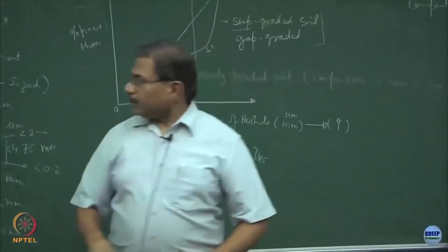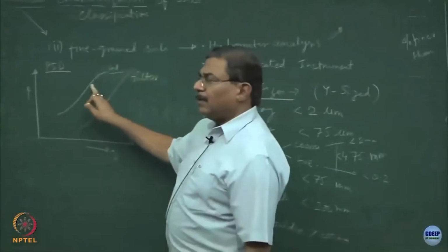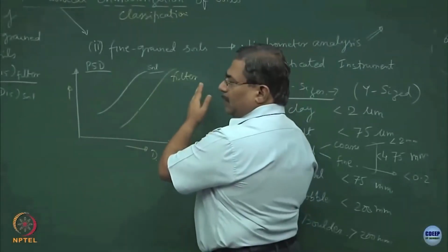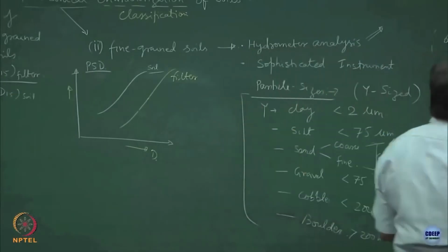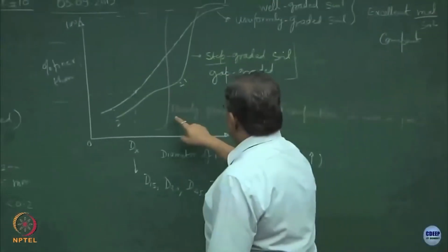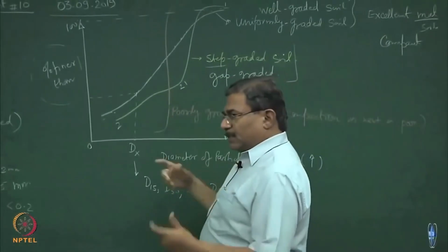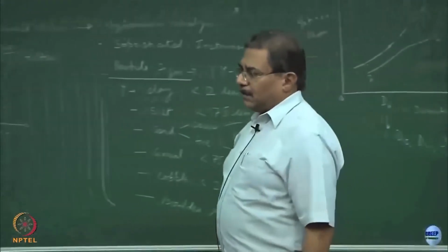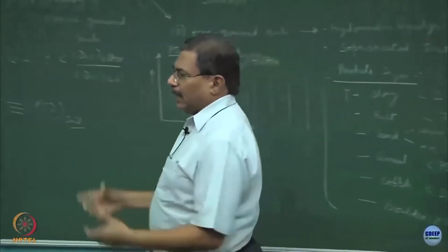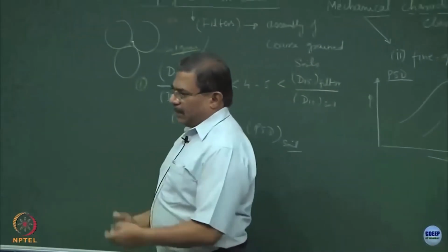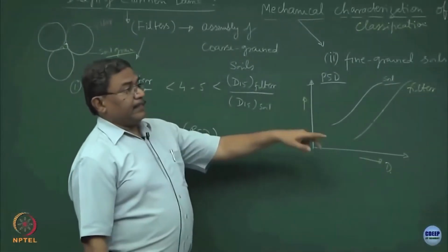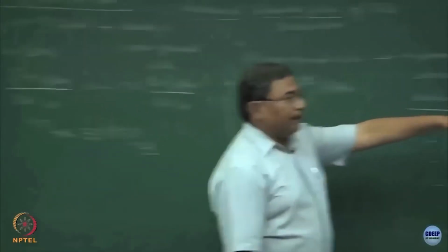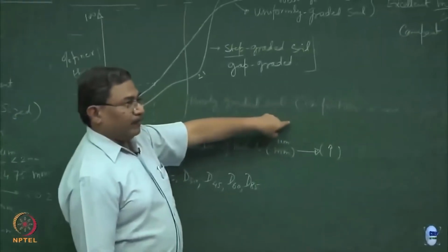Alright, they should be similar, as if they are slightly shifted on the right hand side. Now, if your material happens to be, let us say, a poorly graded soil, which is likely in granular material, sands, you can't have several sizes available in the system. The question would be, I can't achieve the density, because you can't compact it, you can't create a compacted bed out of it.